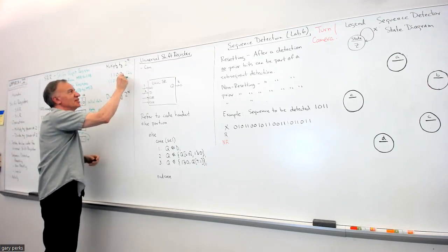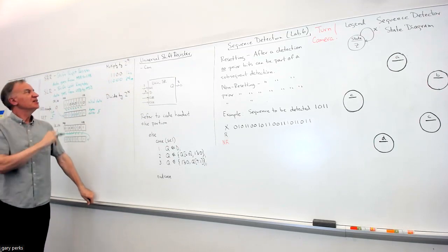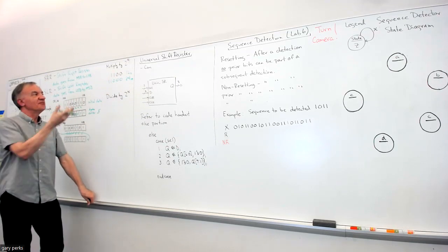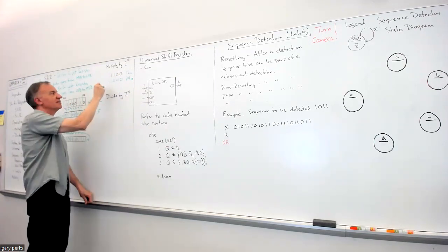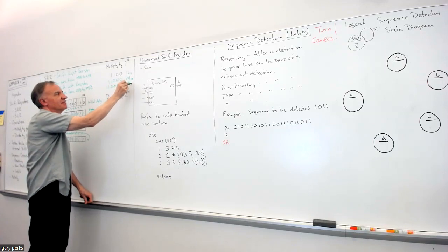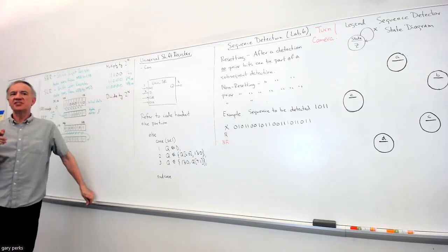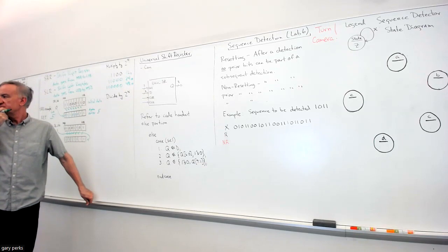So you see, by doing one shift left and bringing in a 0, we multiply by 2. And if I did another shift left, bringing in another 0, I would get 48. So you see, you can multiply by a whole number power of 2 just by shifting to the left the appropriate number of bits.